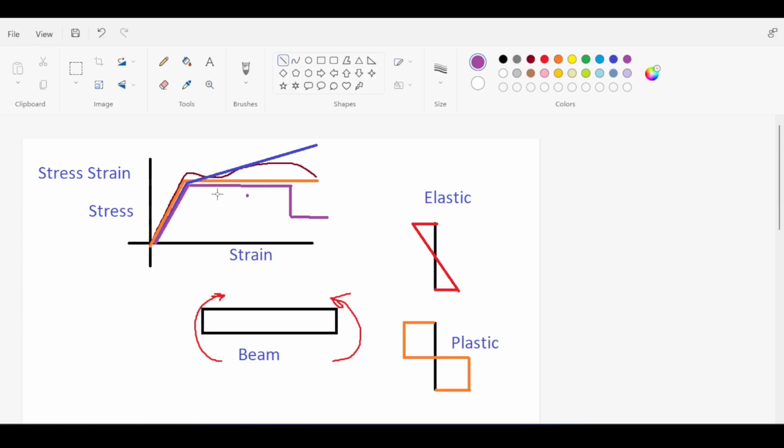Because, for example, for flexural moments, you would have a plastic hinge developing. Speaking of which, I'll be focusing on beams today, so I'm focusing on something called plastic hinges. Now, a beam is a flexural element. If you're in the elastic region, you get the elastic stress response. If you're in the plastic region, you get the plastic stress response. Notice that the plastic stress response here is roughly equal at both points. This point is equal to this point because this plastic stress in the section was assumed using the orange line.